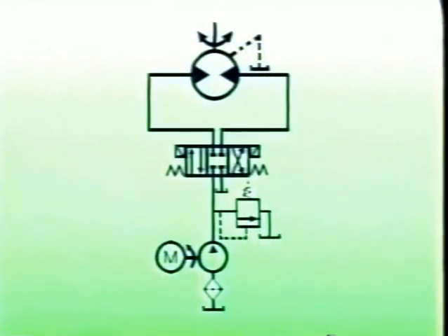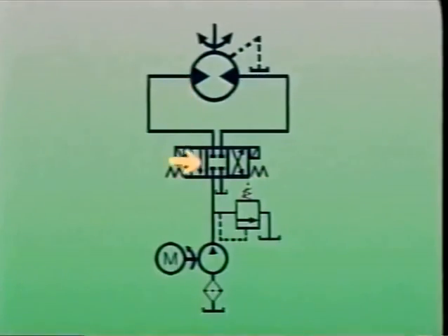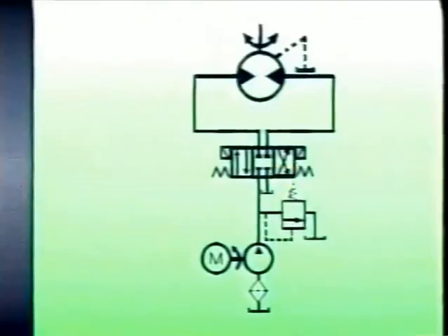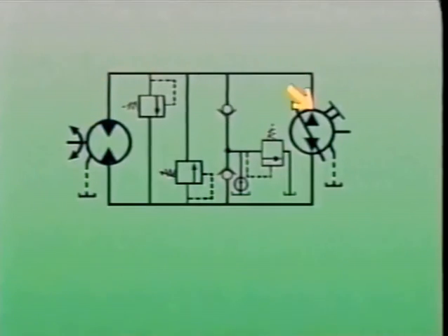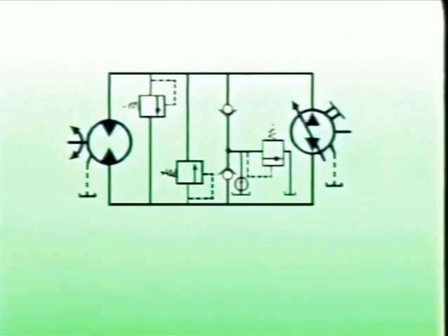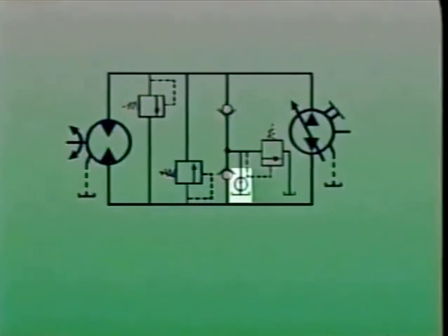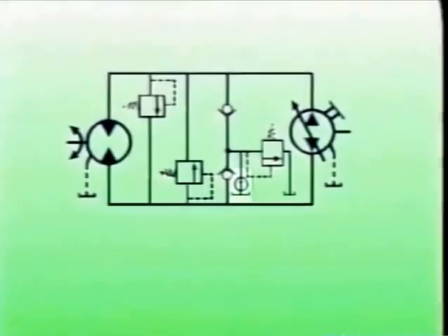An open loop system has the motor inlet connected to the pump outlet and the motor outlet connected to tank. In a closed loop, however, the motor outlet is connected back to the pump inlet. This forms the closed loop. Any fluid leakage in a closed loop is made up by a replenishing pump. Since most of the fluid in closed-loop drives and transmissions is carried in the system piping, only a small reservoir is required. This allows closed-loop drives and transmissions to be very compact.